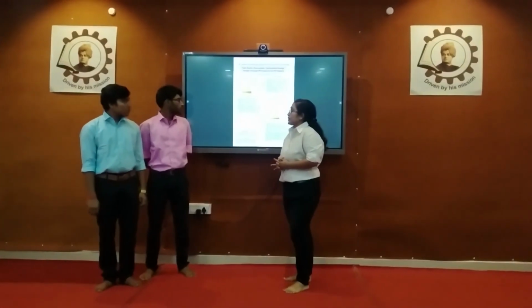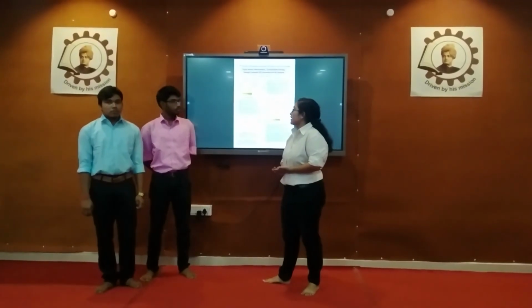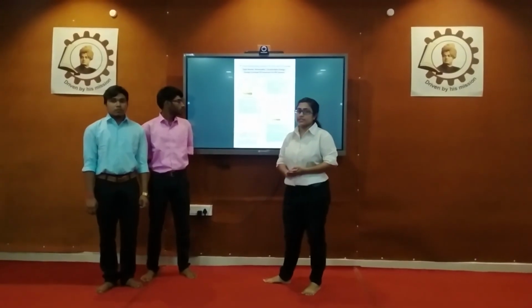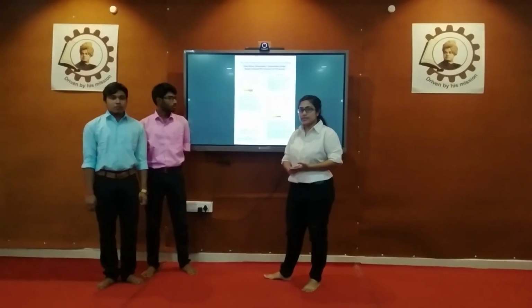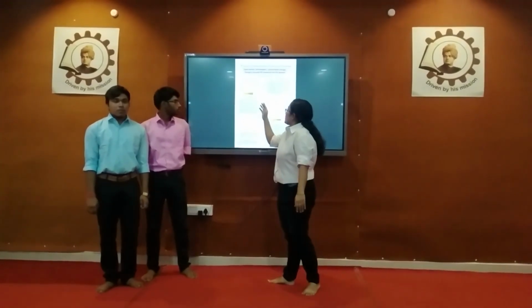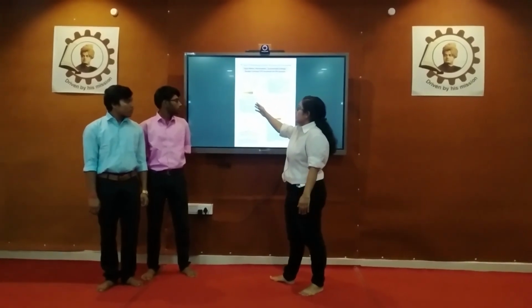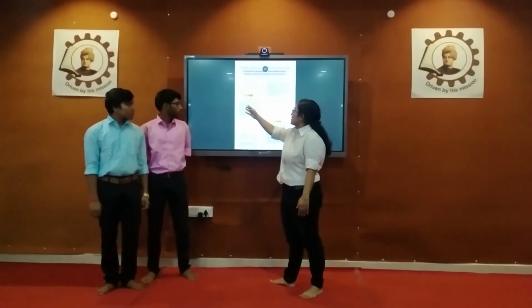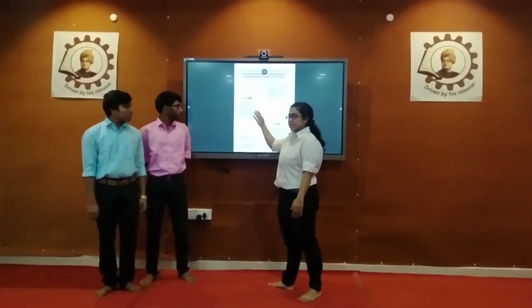Among these switches, there are 6 unidirectional switches and 2 bidirectional switches, along with IGBT and 4 lower cost diodes. In the circuit configuration, the DC voltages V0 and V1 can be maintained symmetric as well as asymmetric as per the requirement of voltage level.